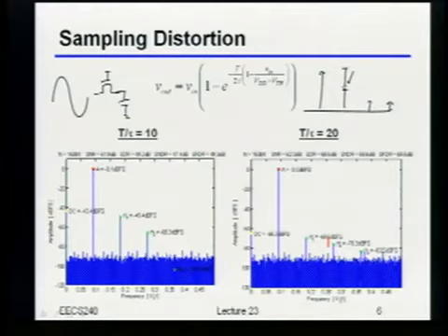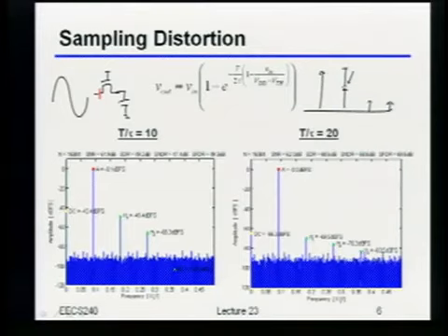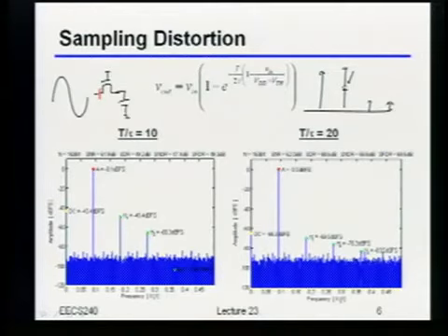So by the way, just intuitively, just to make sure it's clear, why is it that making the switch even faster helps to really reduce this distortion? Why is it that I really care about how fast the switch is relative to this sinusoid? Your VDS stays closer to 0. Okay, the VDS gets closer to 0. You're right, but why is that important? You just need to oversample if you want to reduce aliasing, right?